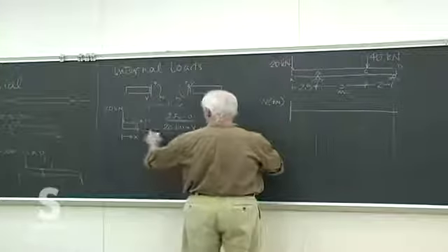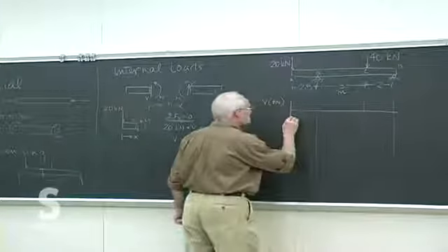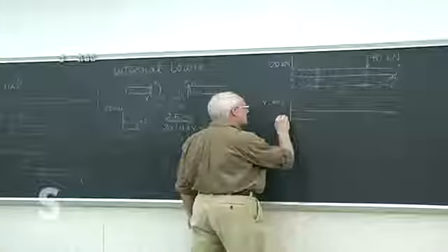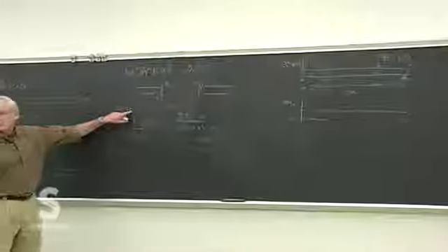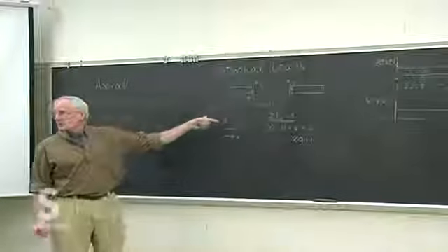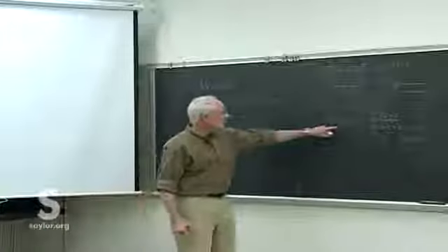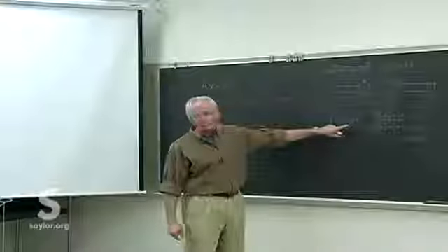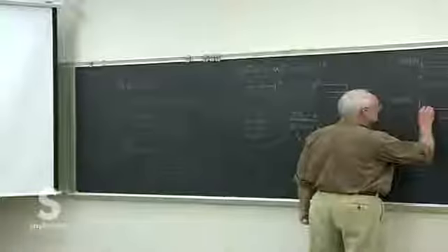And since we put in our drawing the positive direction, whatever value comes out, that's exactly the value that we need to graph. So the minus is already on there. We don't have to reinterpret anything. It's a little bit different than we did last fall. Last fall, I think we typically looked at a down load here that we knew the shear would be up. We drew it that way and then had to interpret it for the drawing. If we put it in positive, just sketch it in positive automatically every time, then solve for it, and now our sign is there and we don't have to do any interpretation.